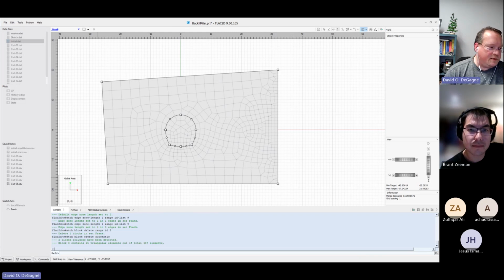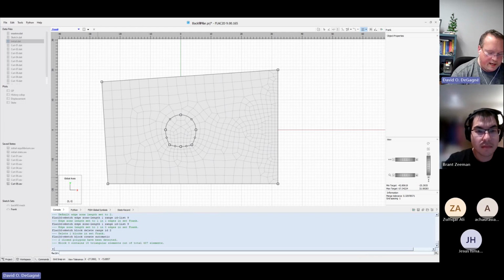Well, in the problem set, we've assumed that you're going to excavate in 6-meter increments. If you want to change that, you kind of have a couple options. If you went smaller, then I wouldn't be worried about numerical instability because I know it works for 6 meters. But if you just took out, what is it, 72 meters? So say you took out half of that, there'd be other things that we would add to the model to ease the model into that.